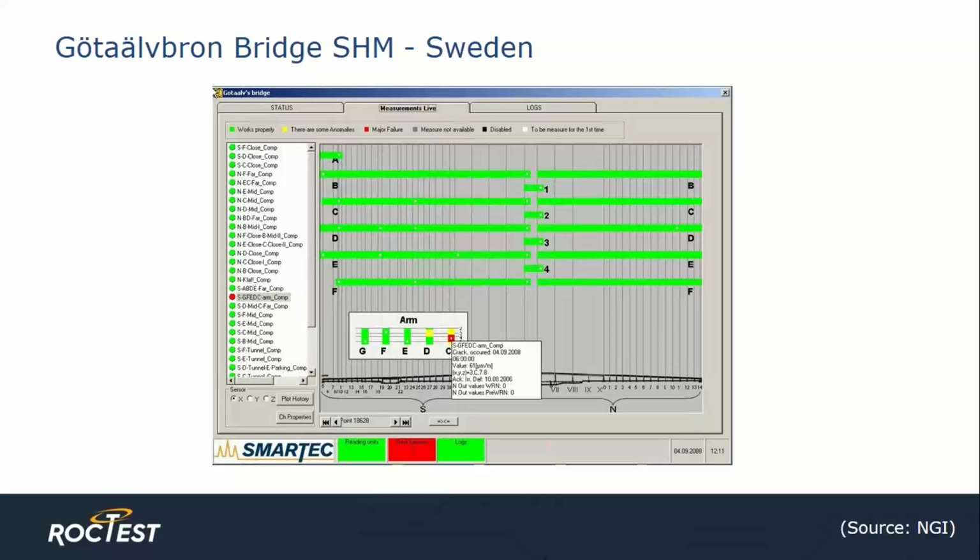The user interface seen here reflects the strain data in all 5 runs of SMARTape. Runs B through F are instrumented support girders. Runs 1 through 5 are transition areas. In the table to the left, locations starting with N are to the north side of the bascule section, and the locations starting with S are to the south side. At the bottom of the graphic, you can see a reference drawing to scale with the data above it.